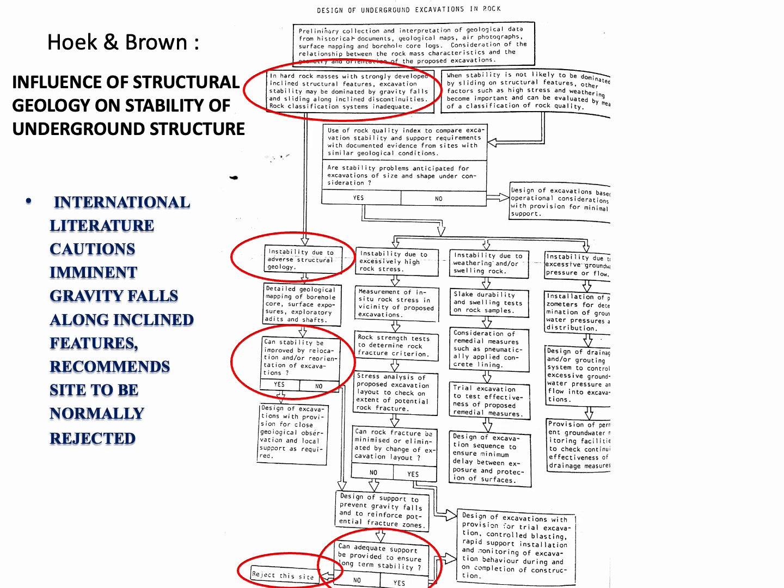Rock classification systems thus become inadequate. So in the case of hard rock masses which have strongly developed inclined structural features, the excavation stability will not be governed by, or designed by, rock classification systems alone.